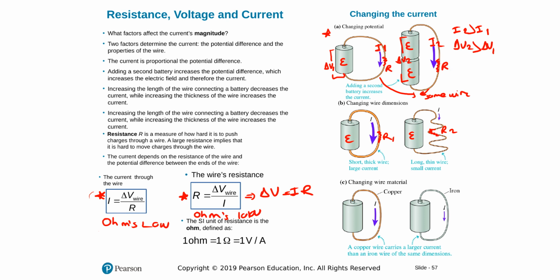Because it's the same wire, thinking in terms of R equals rho L over A, I have the same type of wire, copper wire, let's say. If the length increases, resistance increases, which is what happens here in the second case, a very long wire. And if A decreases, resistance also increases, so a double increase here. R2 is significantly bigger than R1.